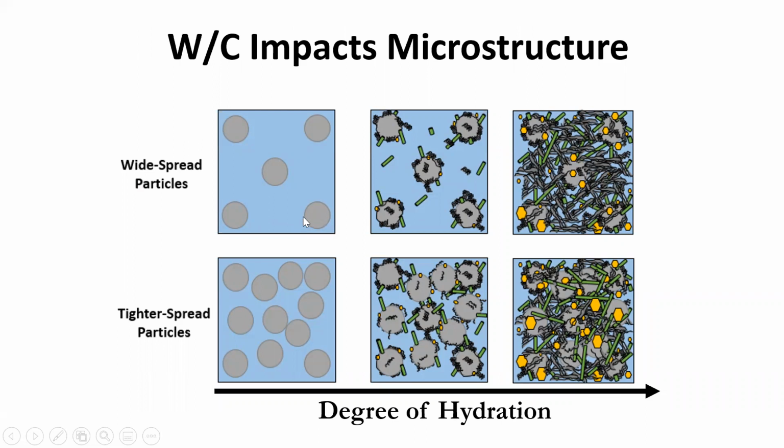So how that kind of looks, when we talked about whitewashing and painting and stuff, if you have less cement and more water, your particles are going to be farther apart. Your cement particles are in the water solution. And so over time, because it's a chemical reaction between cement and water, they're going to produce product on the outside, and they're going to have a harder time to connect. It's going to take longer. These bonds to connect all these particles together with these products are going to take a lot longer to get to initial set and final set.